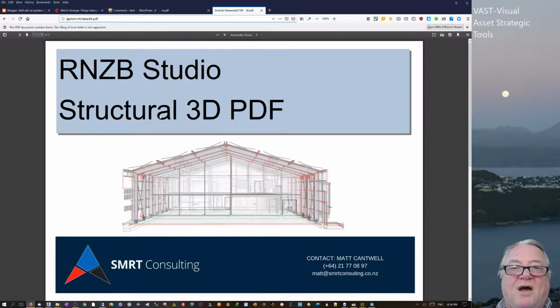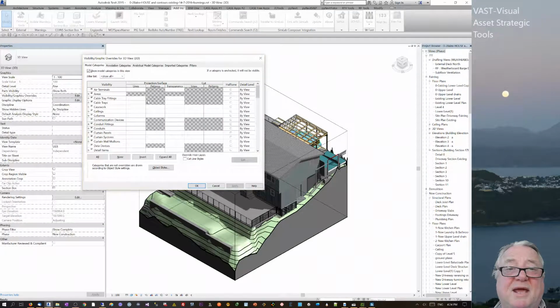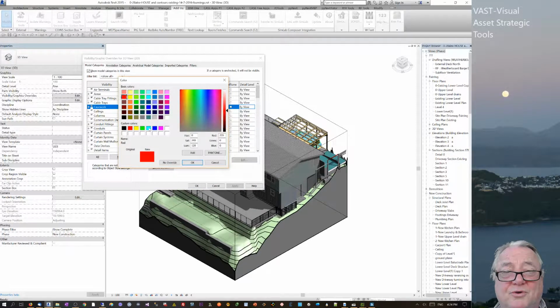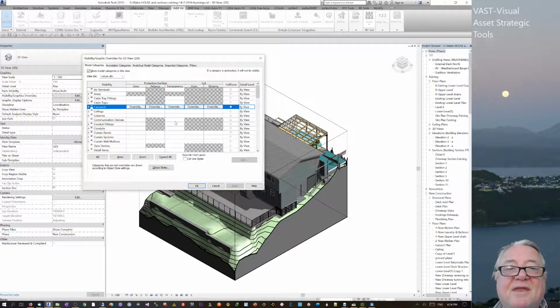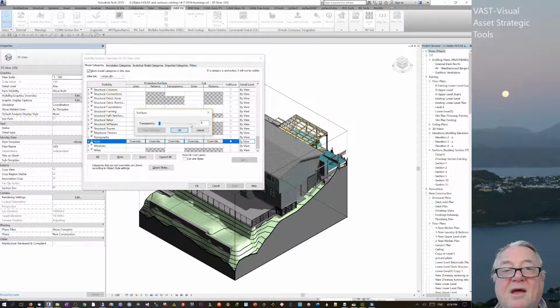Now as the workflow goes, first of all, I'd go into Revit. I would set up my views. I would color them as need be using VV, and I'd say, okay, then I want to highlight the casework. I might overwrite them and make them all red or something so that they stood out, and make it solid so that they were very bold. Now the casework's not being shown at all, so it doesn't really matter here. But the other thing I'd also do is things like walls. I would move the transparency down to about 85 or something like that.